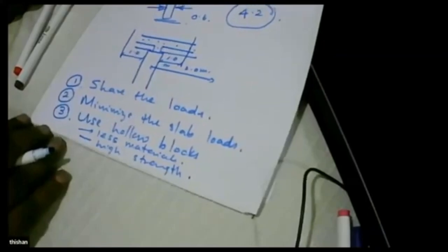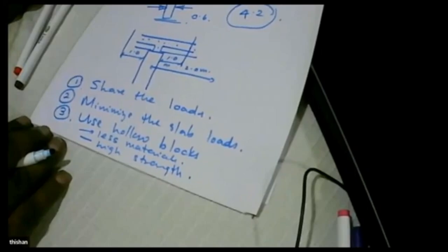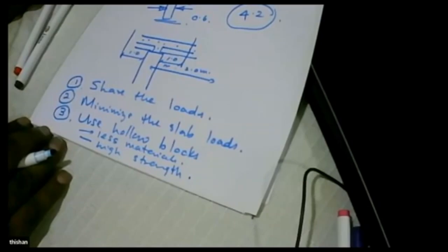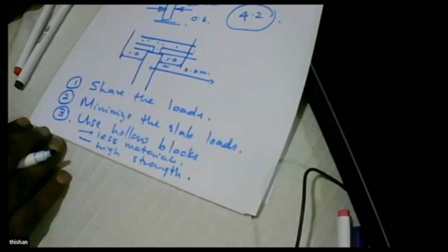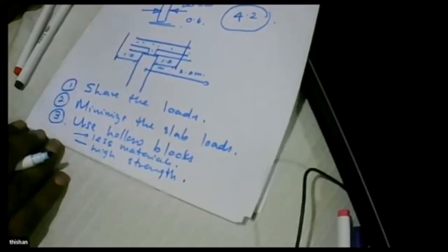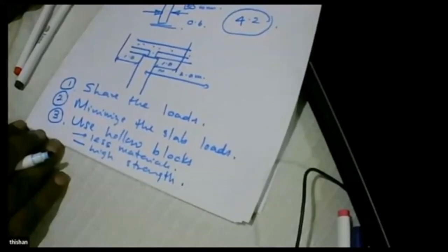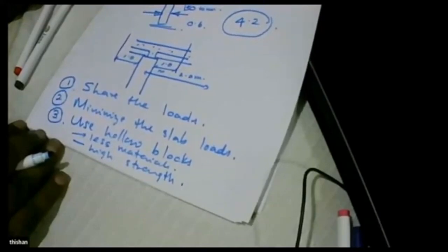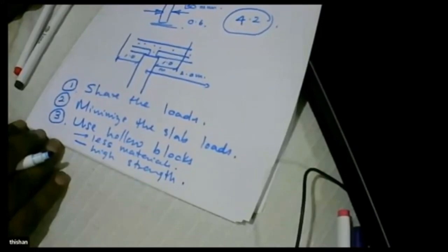So when you do all this, you can see the wall thickness can be reduced to 150 with significant savings on the wall construction, and also it's possible to go up to about 4 floors while having an overall factor of safety of about 4 for masonry. Is that clear, Bandhuka? Yes, that is clear, sir. That's clear, right?